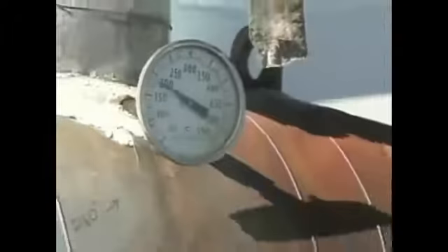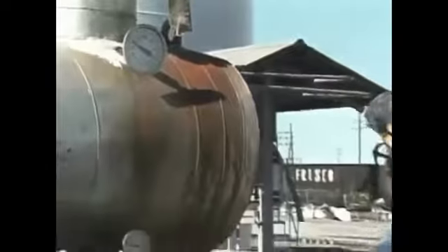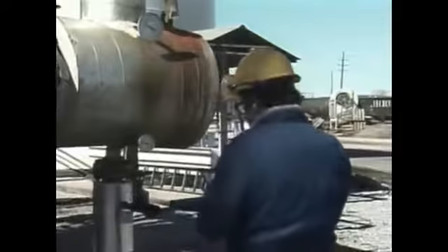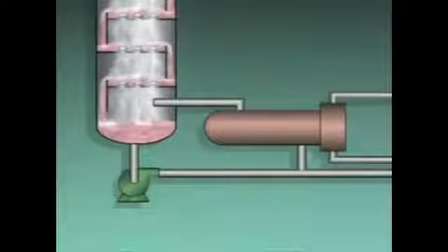To avoid upsetting the equilibrium between the rising vapor and the falling liquid in the column, changes in reboiler operation should be made gradually. If the reboiler in a distillation system isn't operated correctly, problems can occur and the distillation process can suffer. For example, the shell and tube reboiler represented here must be started up a certain way to prevent damage and product contamination.